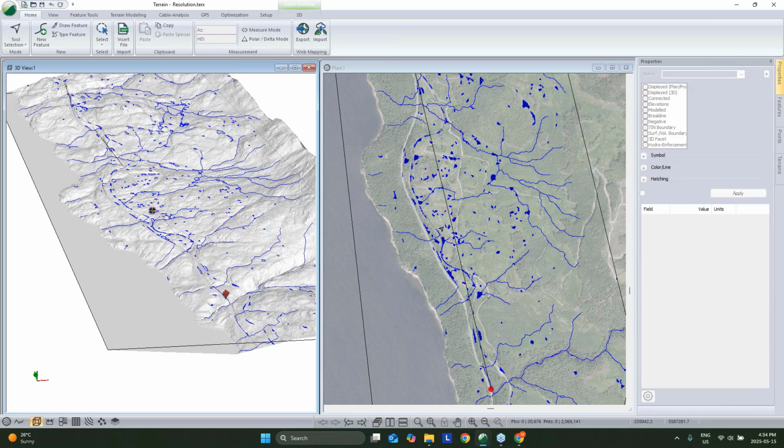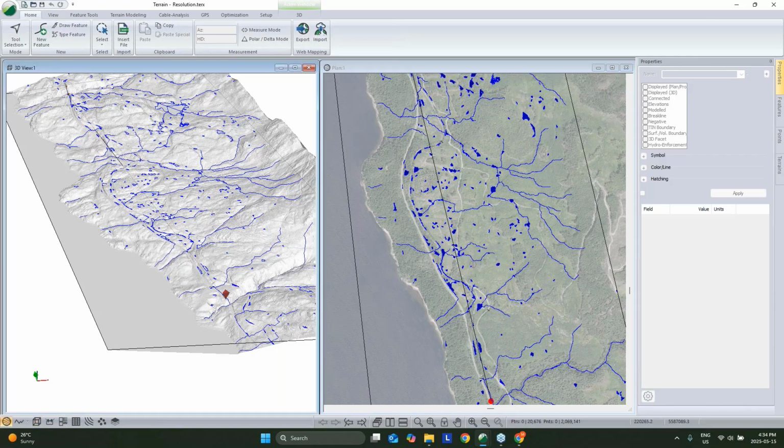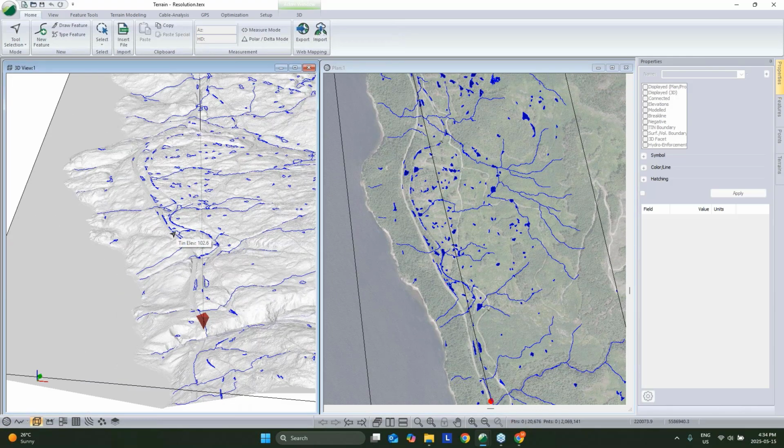Now, to help illustrate this, I think a realignment is a great example to talk about. The Path Explorer isn't really set up to just extract a center line from an existing road. So that's not what it's doing. It's looking at that simplified cross section and trying to find ways to minimize your costs to rebuild that cross section along your topography.